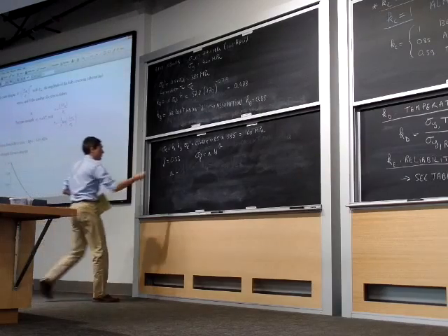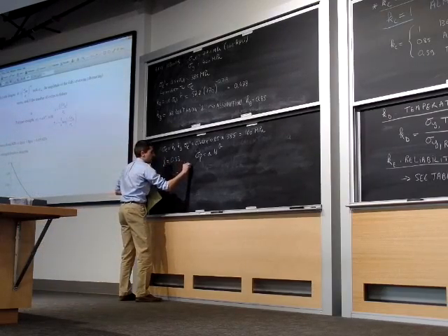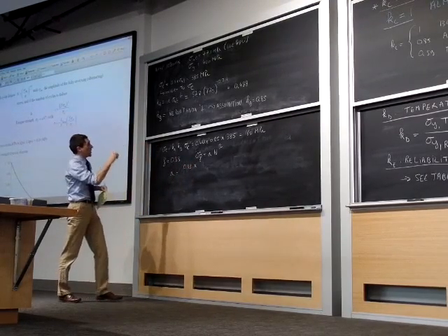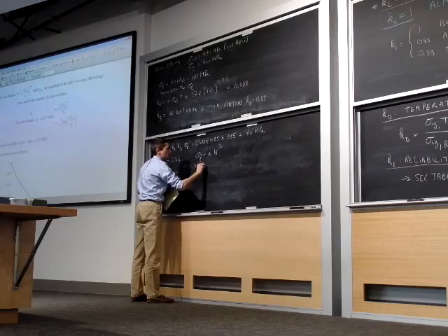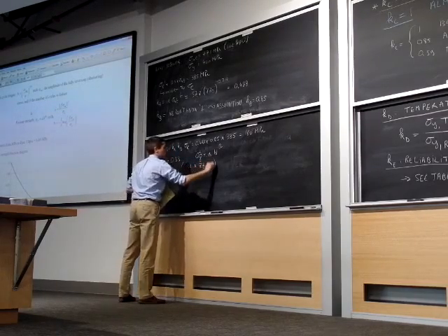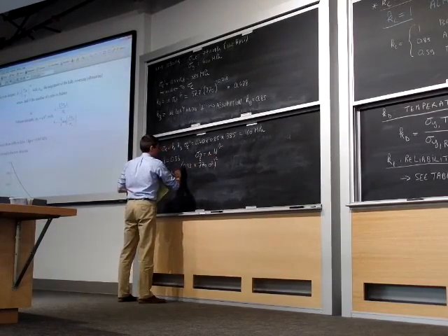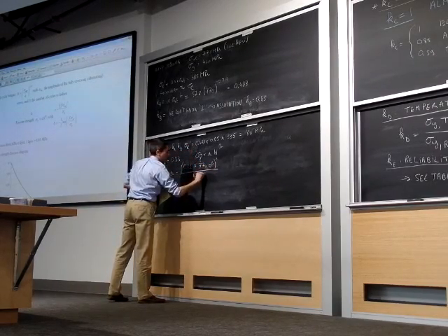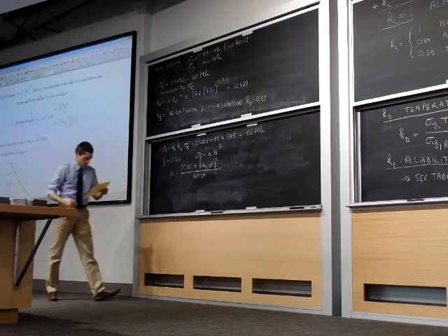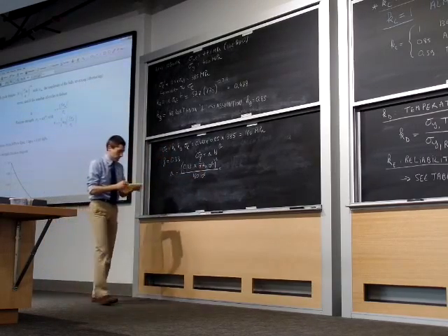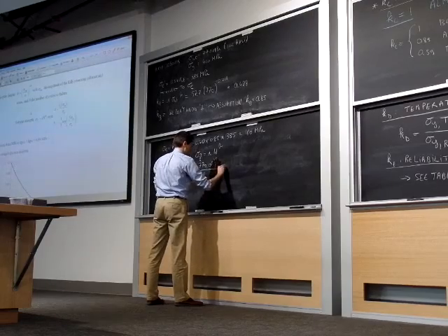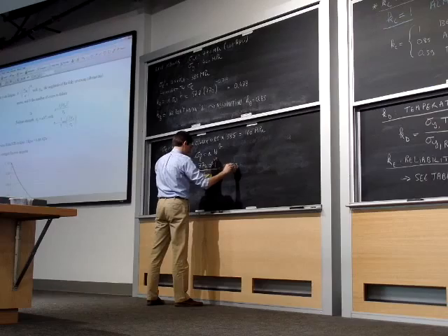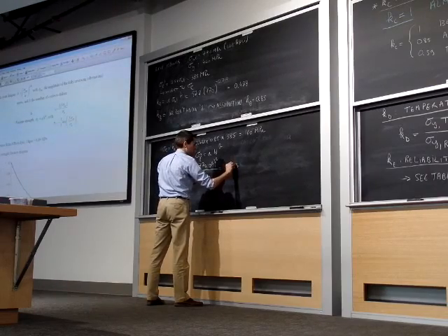A is going to be equal to F, so 0.83, times our ultimate tensile strength, 770, 10 to the power 6, squared, divided by sigma E, which we just calculated, 160, 10 to the power 6. And so A is equal to 2,533, sorry, 53